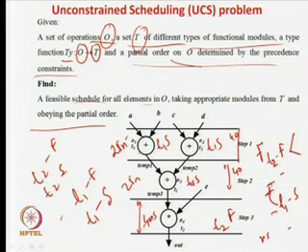In this case, because the 40 nanoseconds is determined by the fastest multiplier I have, I cannot go below it. So, why should I use a 20 nanosecond fast adder, when a fast adder will always take more area and power than a slow adder? If I put in a slow adder, I am not losing anything, because even if I compute the addition in 20 nanoseconds, or even in 10 nanoseconds, I cannot get the answer earlier, because I have a time step of 40 nanoseconds because of the multiplier.